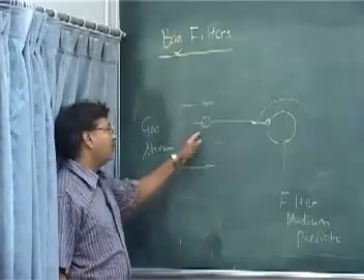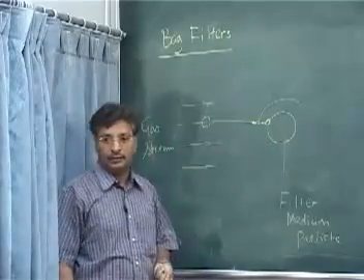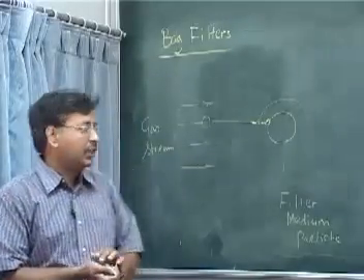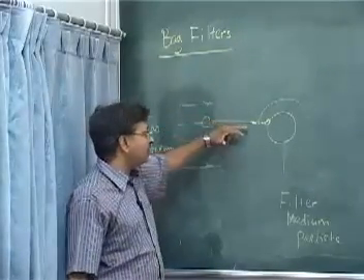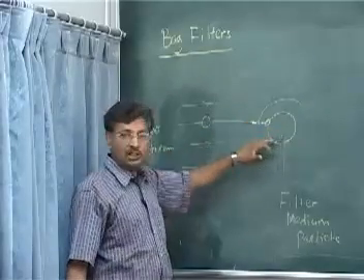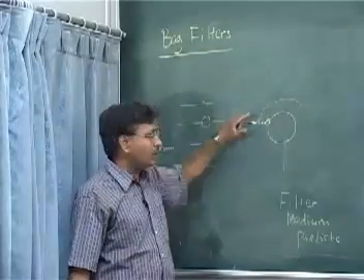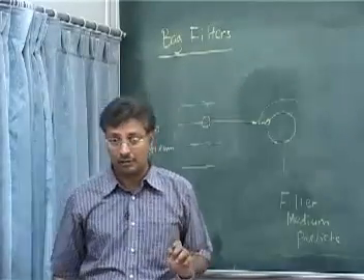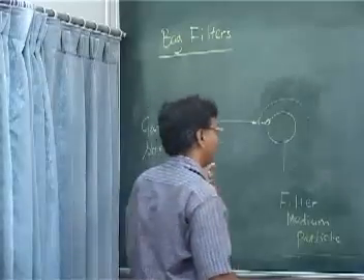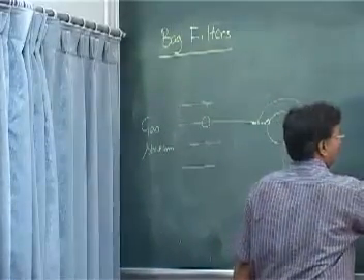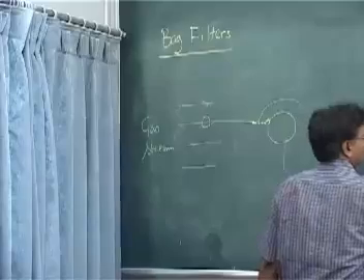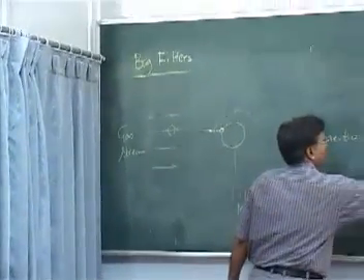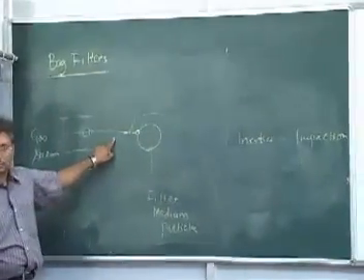Okay. What do we call this? The particle is moving because of its inertia. The gas will react to the disturbance. The gas stream will move up. The particle because of inertia will continue to move. That is called impaction, if you recall. Okay. So the first mechanism is because of inertia. This is impaction, what I have talked to you about.